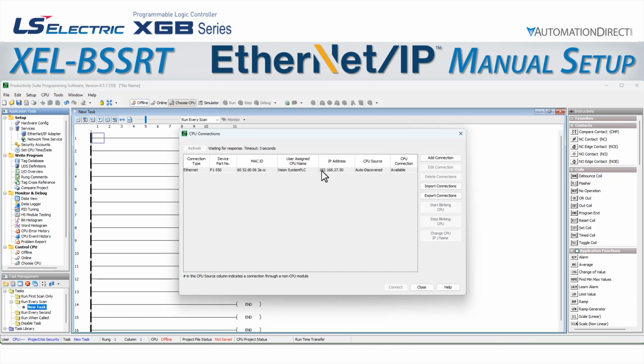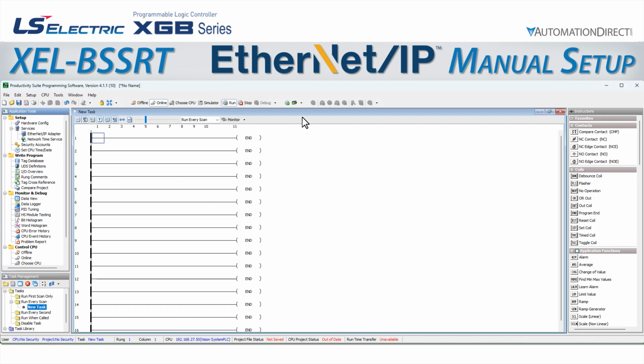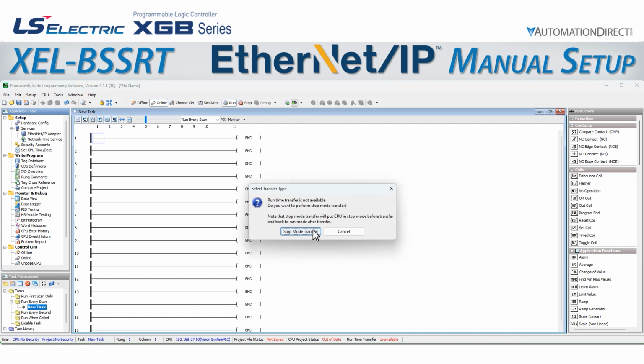The AutoScan in Productivity Suite shows us that our P1550 is at 192.168.27.50. We will select this, and when we accept it, the software asks us if we want to use our PC project or the project already in the PLC's memory. We have just created our project in the PC, so we will select No, Use PC Project. We can then transfer the project to the P1550,